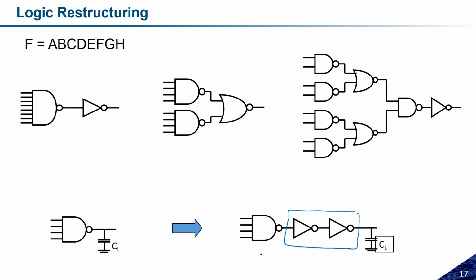So always, in a simulation setup, if you are simulating some circuit, you have to add some buffer before the circuit and after the circuit. Definitely this buffer is not going to affect the functionality, but the loading effect can be overcome. So this is the importance of buffer insertion in the circuit.